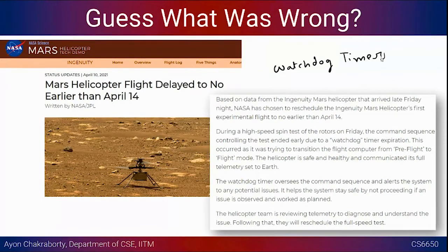Okay, so nobody is reporting it, and the way it is built is that once your program is not reporting back to the watchdog timer, it will think that something is wrong, so it will reset the entire system. Okay. So wrong could be many things, starting from memory corruption to infinite loop. Many things could be there. Is it clear? Yes, sir. Okay.